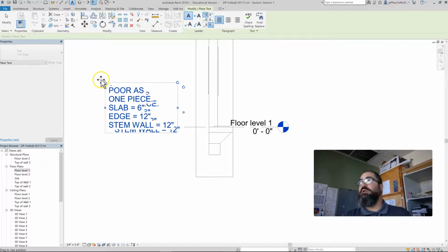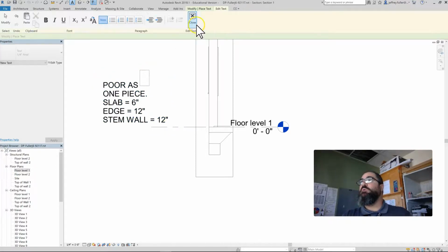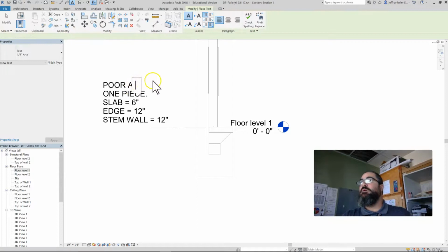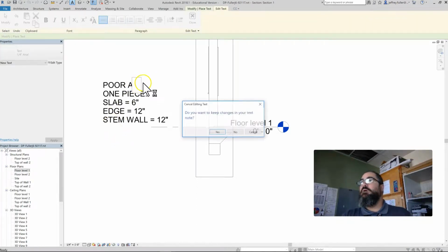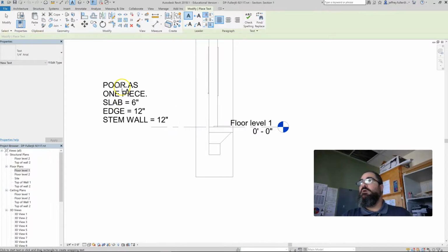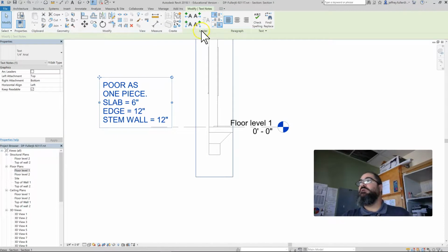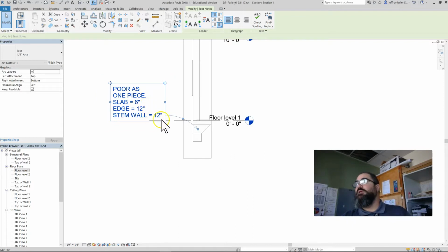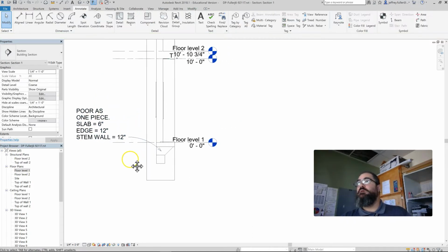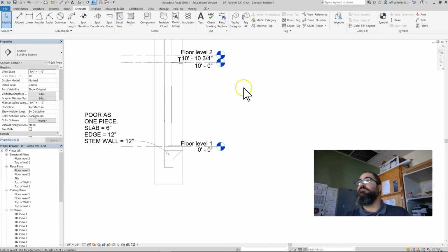And of course we also want a leader pointing to that, so we're going to use, whoops, select that and select our leader style here, curve to the right, take our leader and stick it right in there where you can definitely see the arrow at the end. And they'll know what we're talking about. So that's it.